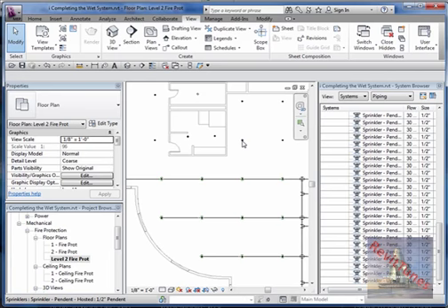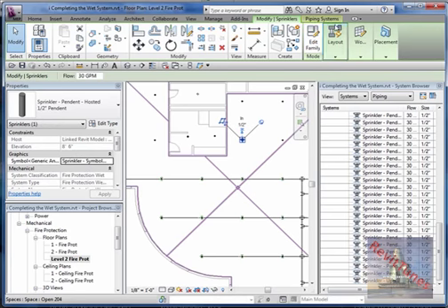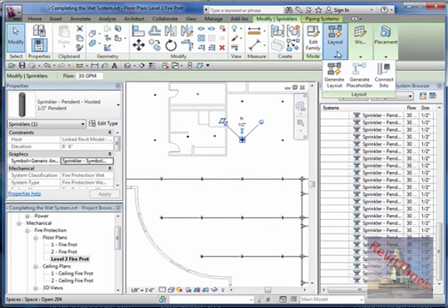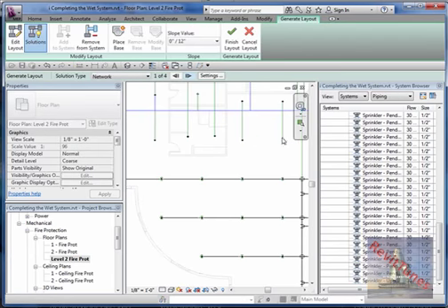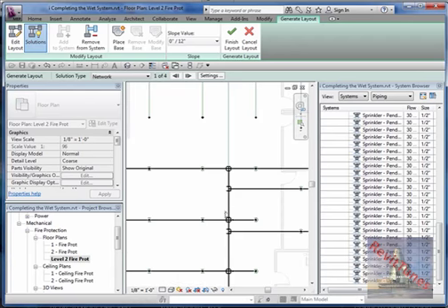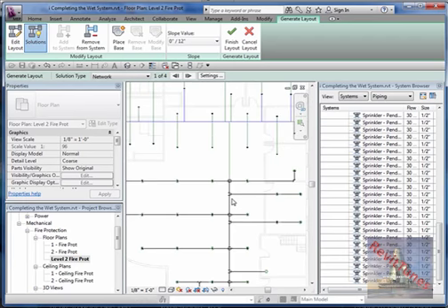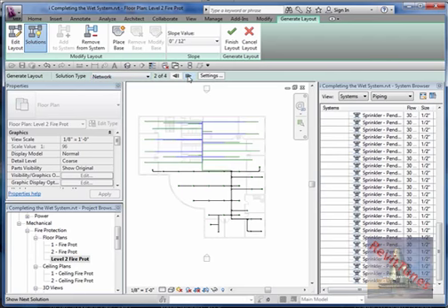Anyways, so again, I could touch one of these and I get the same possibility, the previous command or this new command. So I could say generate piping, and because it knows it comes from this main, because I started by selecting this group of existing piping, it knows that's the same main I'm gonna use. And again, you could swap between these 3 different options, and I wanna choose the network, and you could swap here. I wanna use option 3.